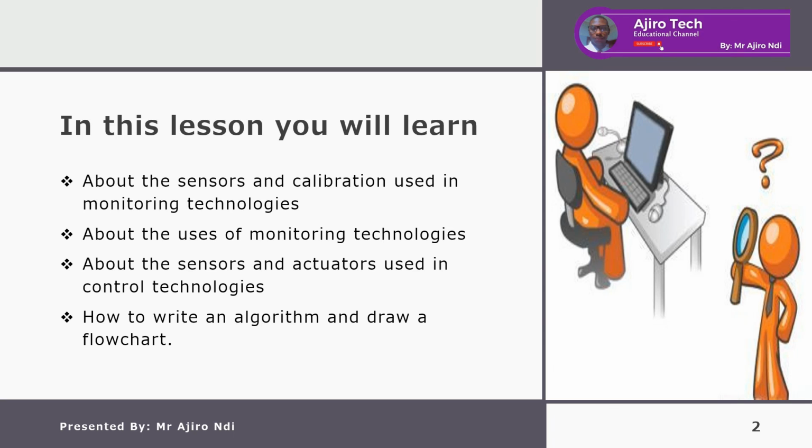We said that for calibration, we have methods used to calibrate devices. We have three: 1-point calibration, 2-point calibration, and multi-point calibration. Calibration is making sure that when, for example, a temperature sensor is used to measure the temperature of boiling water, it causes the computer to output a value of that number of degrees.